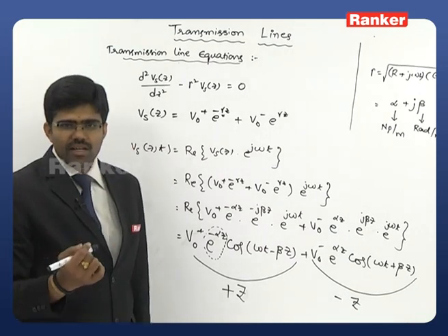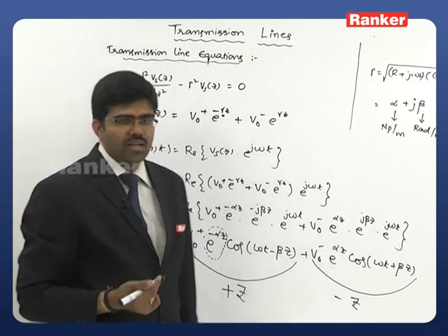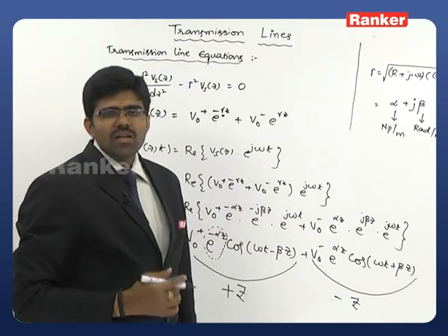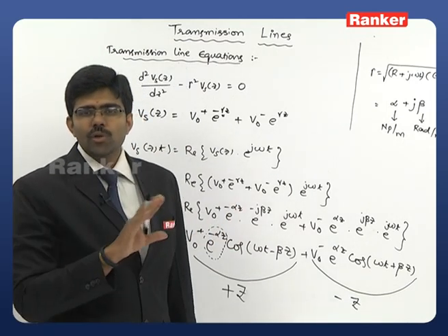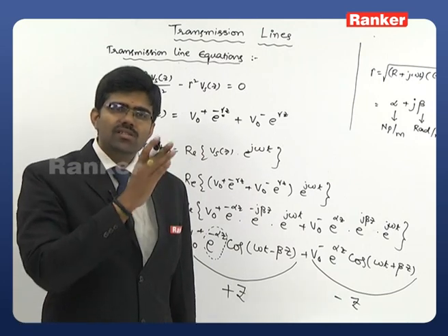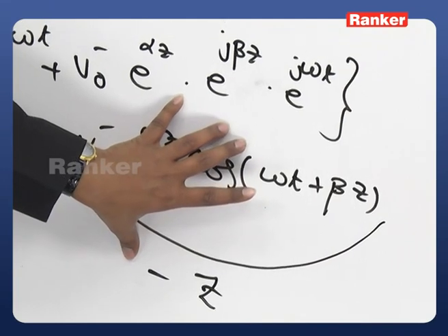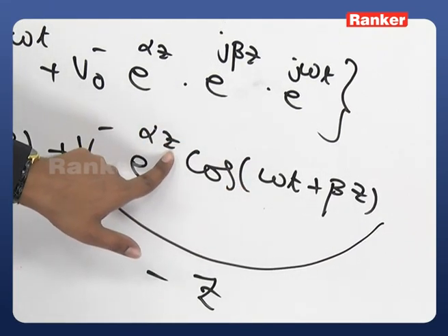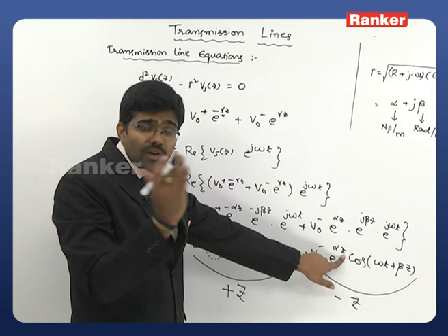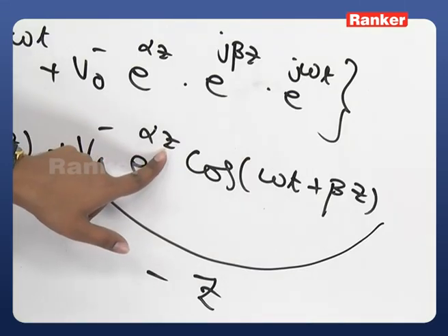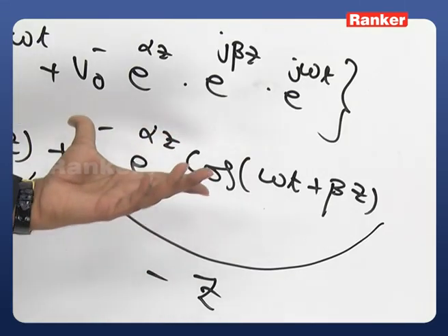And for an infinite line, just a simple point, what about this equation? Clearly remember, for an infinite line there will be no reflection, since the wave is infinite, it's always the positive wave that will be there, and this entire term will vanish. Put z equals infinity here, so that when it is reflecting, if you put minus infinity, obviously this term becomes 0, right.